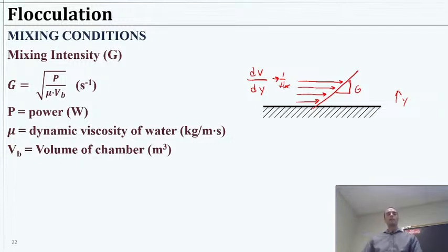So if you had a 1 horsepower little motor and you're trying to stir an Olympic swimming pool, you're not getting much mixing intensity, all things told. And now if you did that in my 1 liter bottle of water, that's probably going to be quite strongly mixed. You can intuit that very easily, and you can see why that volume term is important there.